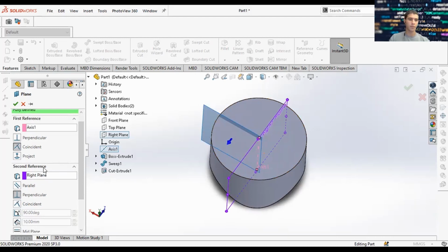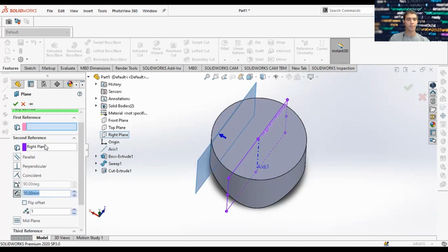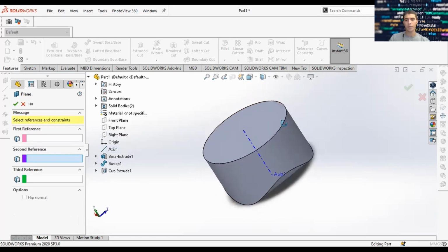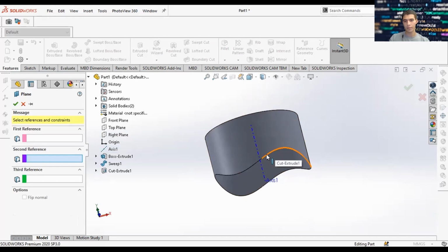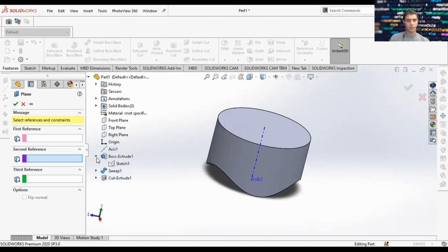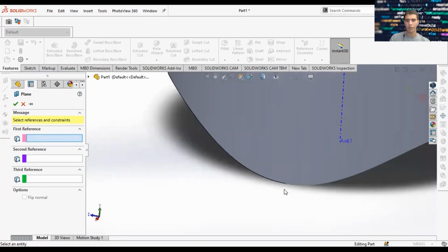And so this reference plane, you want to set it at the beginning of the curve-driven function. So we bring back our curve-driven function, and we set this dot as the initial point.